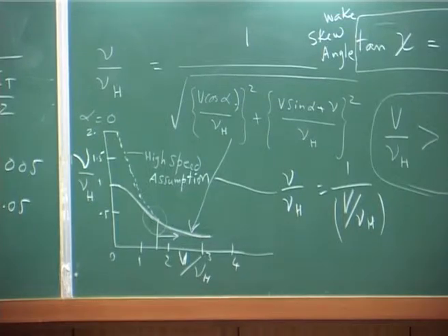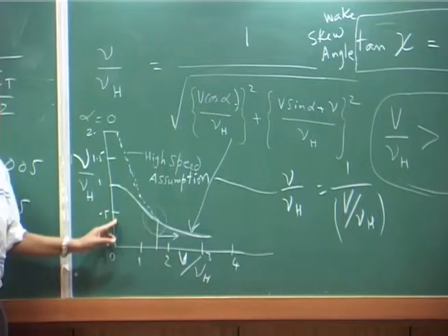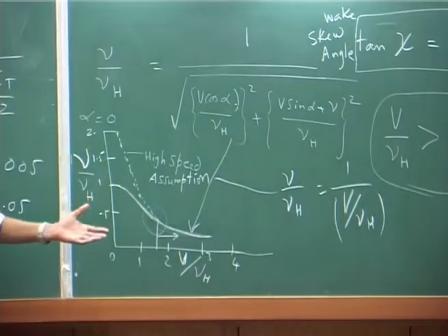0 to 0.1 forward speed, which is the advance ratio, forward speed divided by tip speed. If it is in the range of 0 to 0.1, you say that is transition. Is it clear? During that region, the wake is close to the rotor and of course getting skewed. As you increase the speed, the wake goes back, okay. So if you want to get a quick answer, what is the inflow? You can't make that assumption in this zone. Beyond that, it's okay. Is it clear?